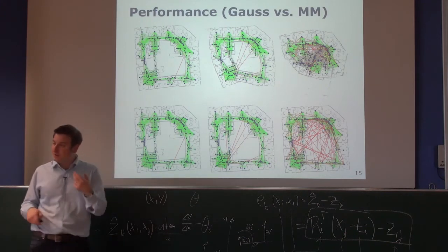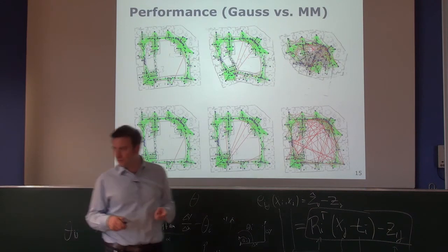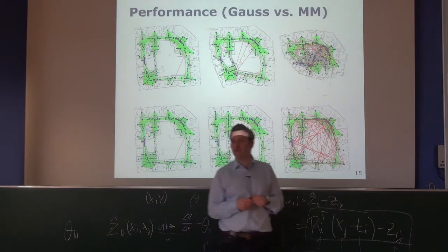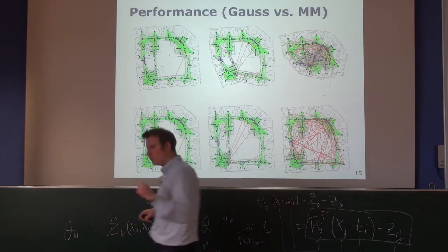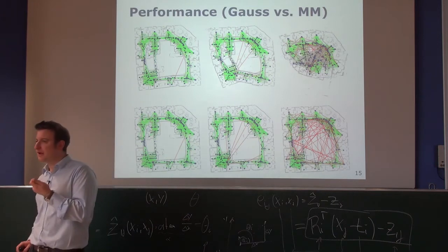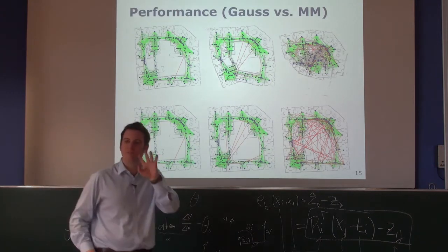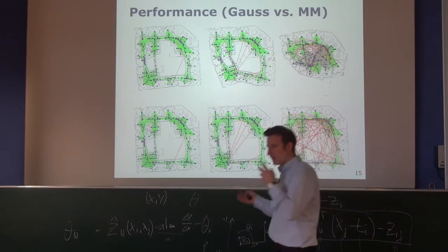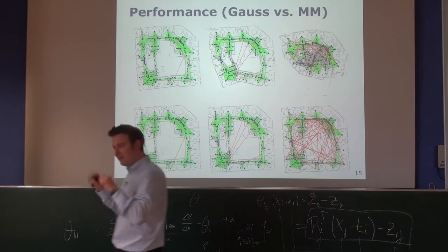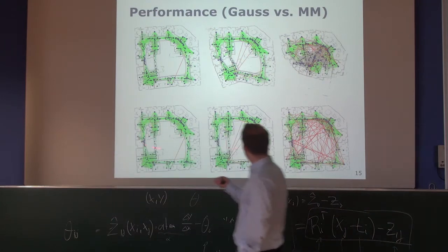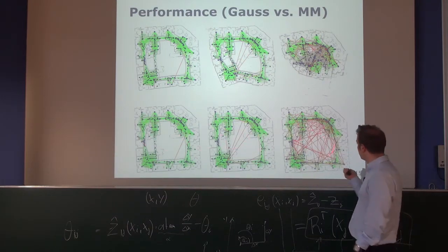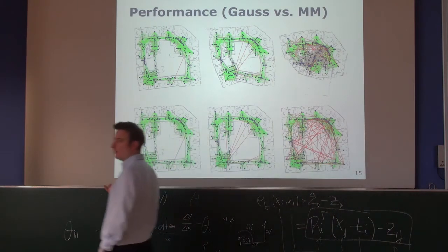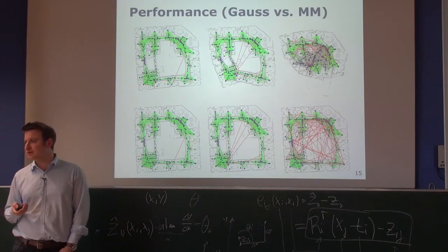If you do that, all these constraints are bimodal constraints. One is the original constraint that you measured, and the other one is a flat Gaussian with a large uncertainty, which the system swaps to if the constraint is an outlier. There's a very high likelihood it will swap to that, unless you have a bad initial guess and the bad initial guess is in line with the outlier, then you may run into problems. But if you do this, you can add 1, 10, 100 constraints, and those are constraints which simply swap to the other mode and don't harm the optimization much.